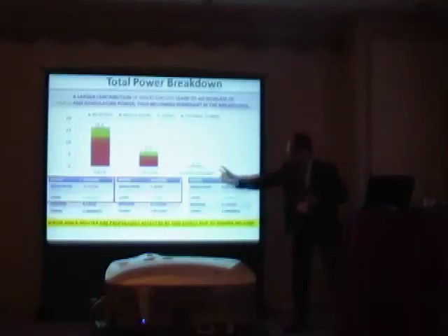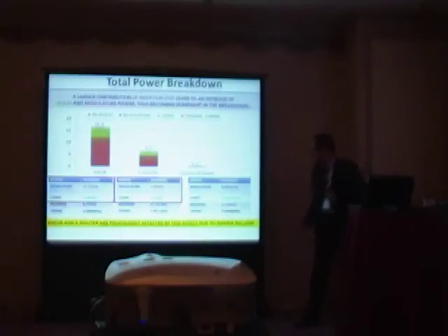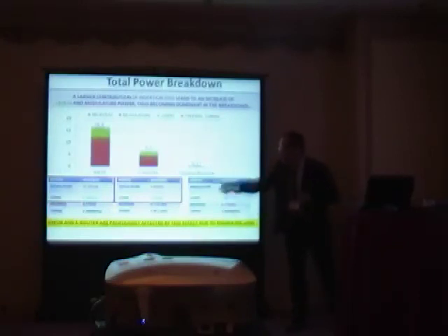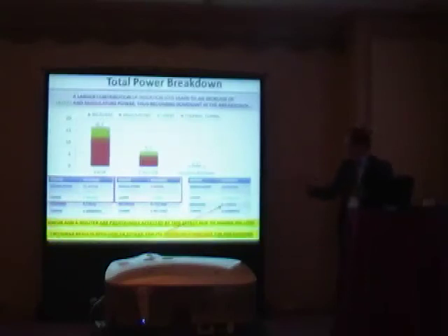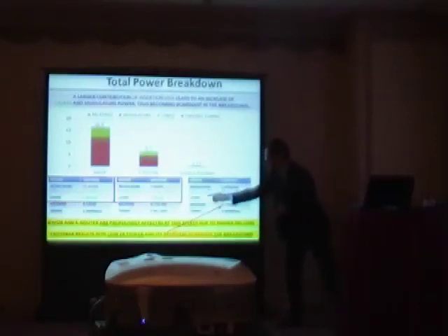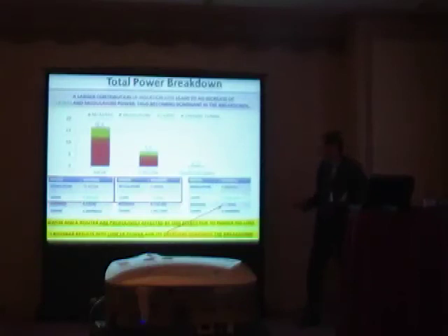Here, since the G-board and the lambda router are characterized by higher insertion loss, in the breakdown the modulator and laser powers are preponderant. Not surprisingly, this is the key feature of the crossbar. The crossbar has the minimum insertion loss, and then the contribution of lasers and modulators is certainly lower, but the receiver power is dominant.